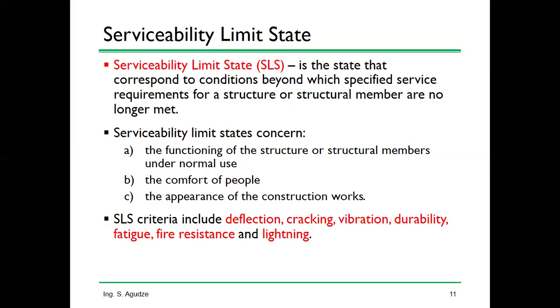The state that corresponds to conditions beyond which specified service requirements for a structure or structural member are no longer met. So here we are looking at more of the service requirement, right? So the serviceability is concerned with three major things. One, functioning of the structure or structural members under normal use. Two, comfort of the people and three, appearance of the construction works.